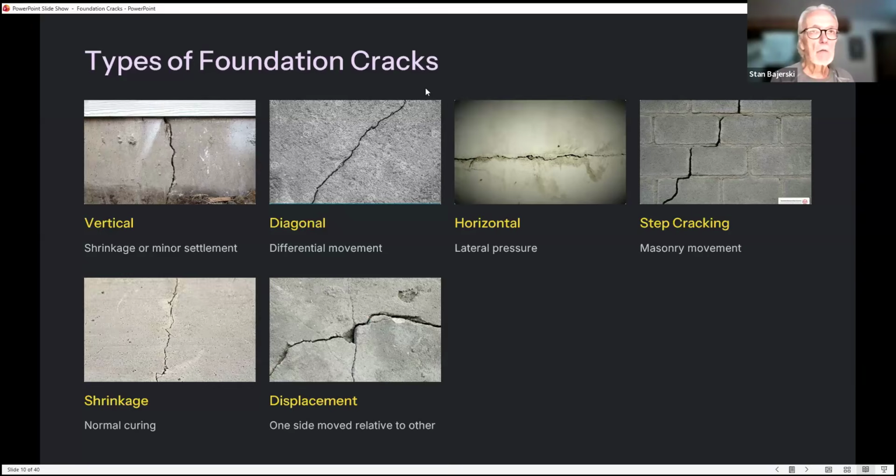First of all, are we curing that foundation properly after it's poured, if it's poured concrete? What type of soil have we put that foundation in? And you have to understand that we're putting a lot of weight on top of that foundation with the wood structure. So settlement cracks and shrinkage cracks are going to happen.